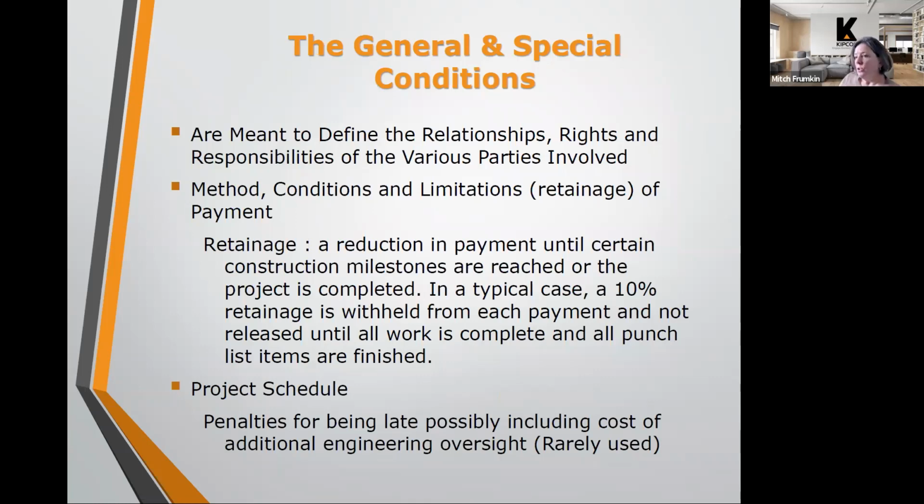So, as I mentioned, there are general and special conditions within the bid documents. These conditions are very important to have reviewed and to make them part of the contract, because they define the relationship between the parties and who is responsible for what, who is responsible for notifying tenants, for example, of the project schedule.